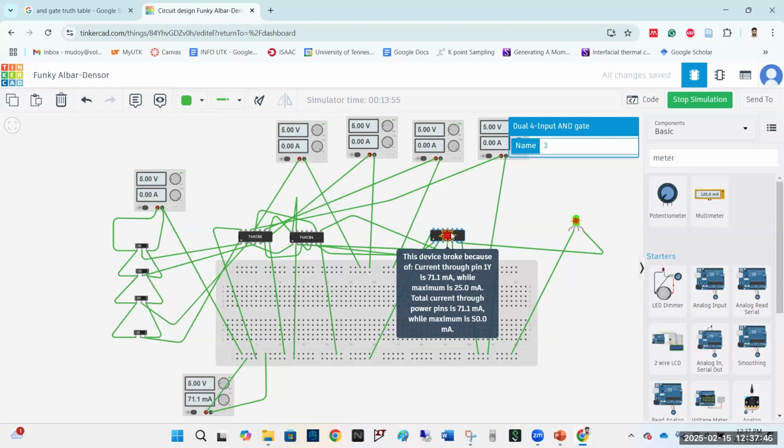Okay, I wanted to describe one thing, how this can be a possible fix. There are different fixes, but this can be one. We have an AND gate and suppose it is producing 1 or 0. When it's 1, what does that mean? It is producing something like 5 volt, or it can be lower, but near 5 volt. An LED cannot handle that actually.